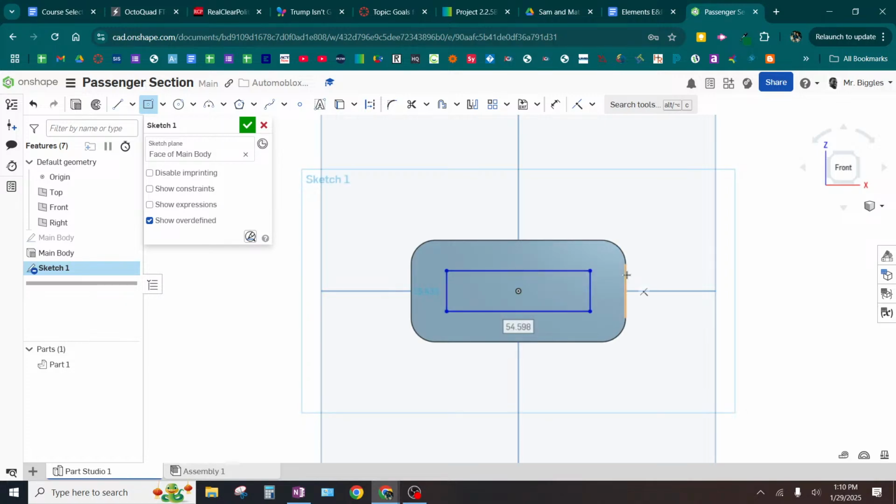Now, this is a hole. So when measuring something like this, we're going to use the top teeth, because they go inside stuff. So I'm going to put my teeth in there, and I'm going to measure the width. Be careful. If you drag your teeth all the way to the very edges, those corners are rounded. You don't want that to mess up your measurement. So you're going to have to put your teeth kind of in the middle. Just do your best to make sure it's actually straight. Maybe try and line it up with something else.